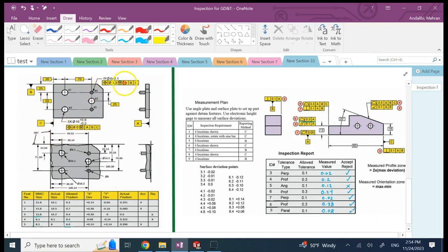And I have provided the position tolerance for the pins, and I have provided the position tolerance for the holes. Now when the part comes out, it comes out like this one at the bottom, again with exaggerated deviations and exaggerated imperfections. And these are the measurements that I make corresponding to those basic and other dimensions. So now with those, I want to see whether these 2 position tolerances for the pins and these 3 for the holes would pass or fail.